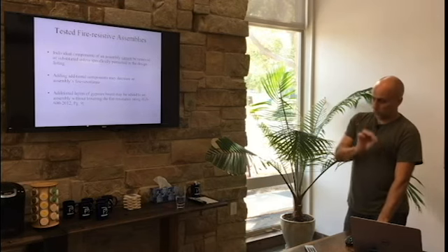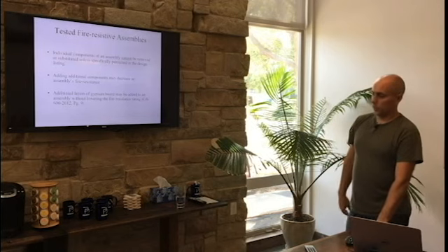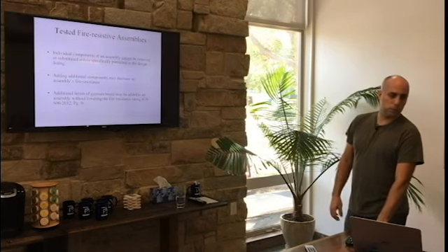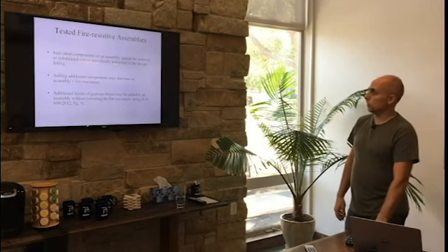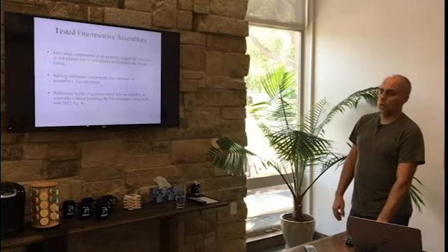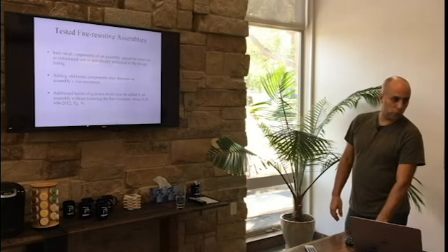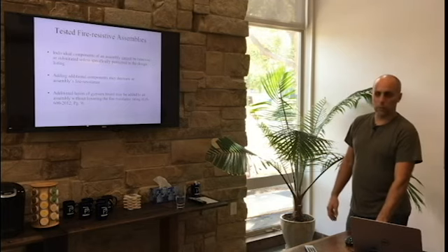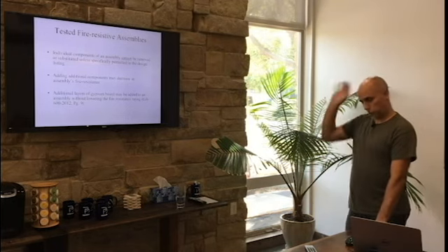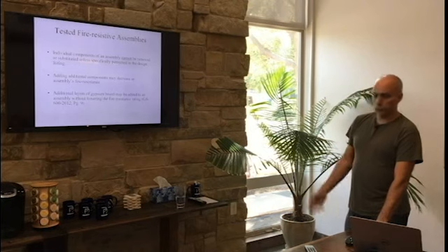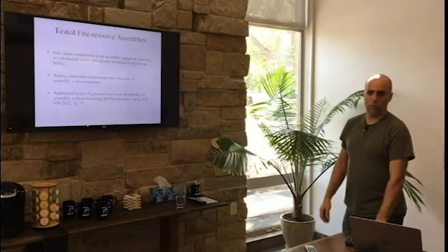A couple things that are different, however, or clarifications: you can always add more gypboard. That is one thing that they say in all these assemblies, the ICC and in the Gypsum Association's directory. If you want to add 18 layers of gypsum board to a 1 hour assembly because you want to do it for, say, an STC rating, for sound prevention, go right ahead. More gypboard will not lower the resistance of a fire resistive assembly.